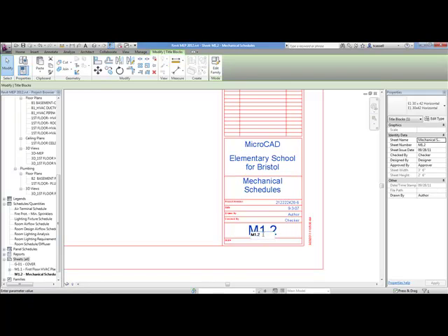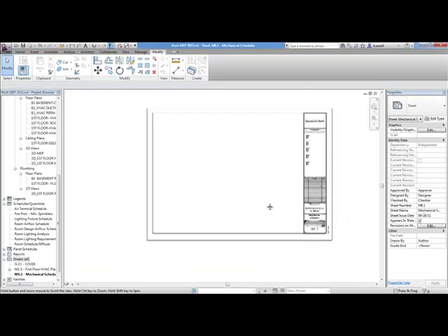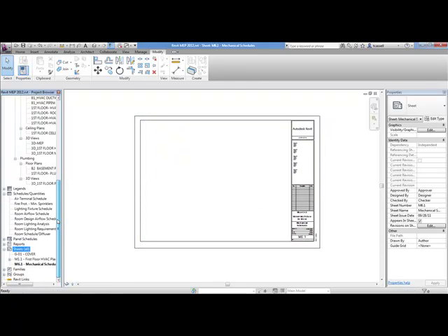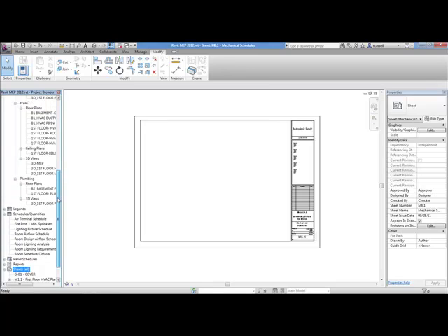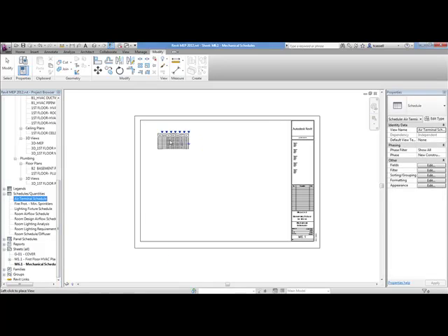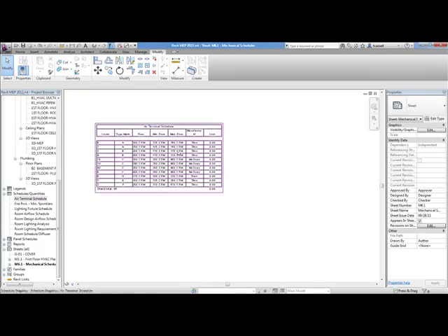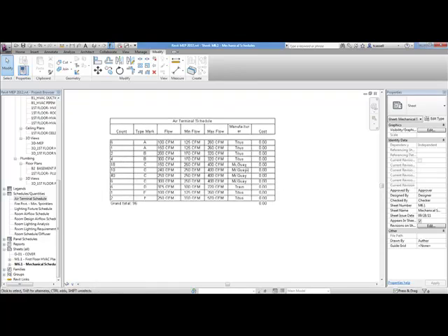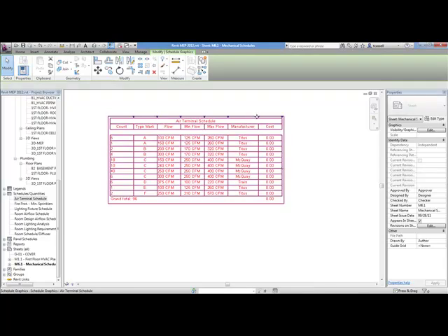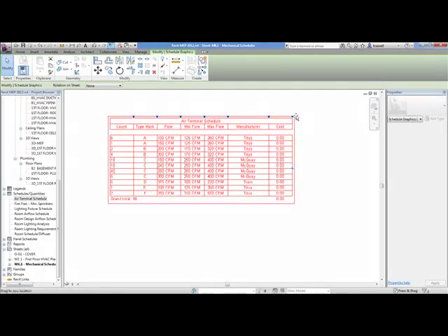Okay. And mechanical schedules are M6.1. Say that's my category for mechanical schedules. So all that information, again, just click and enter. Not much different than using attributes in AutoCAD, however they're much easier. Put my air terminal schedule on, it's just drag and drop. It comes in formatted the exact way you saw it before. I might need to make some minor adjustments, but when you do, it automatically corrects itself.